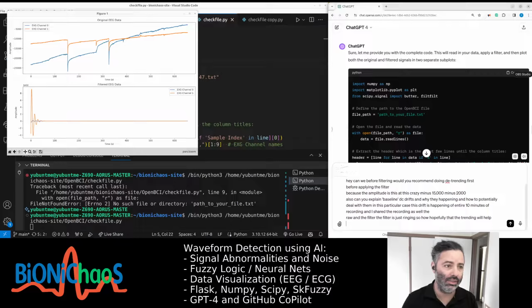I think it's to do with how the electrodes are being placed. So essentially, you need to monitor. Ideally, before you start recording, you monitor impedance. So you monitor how well the electrode is connected to your head. Also, could you mention monitoring electrode impedance when recording EEG and how it's important or not?